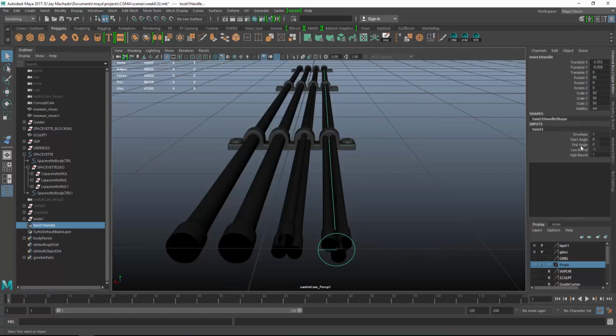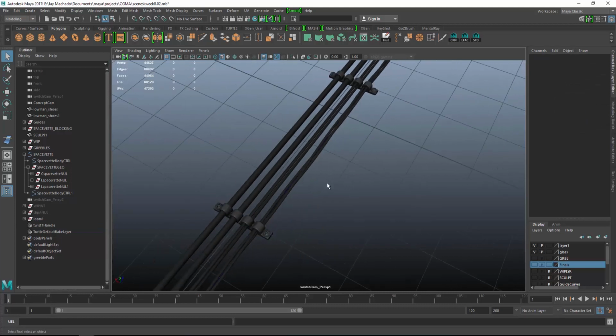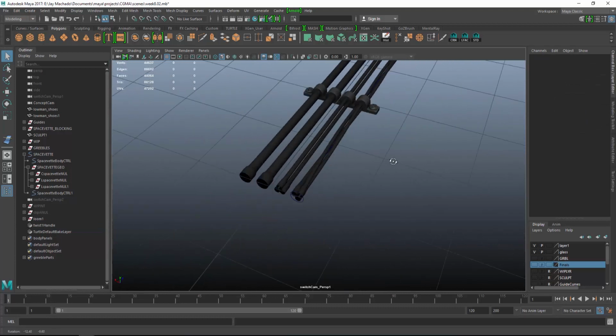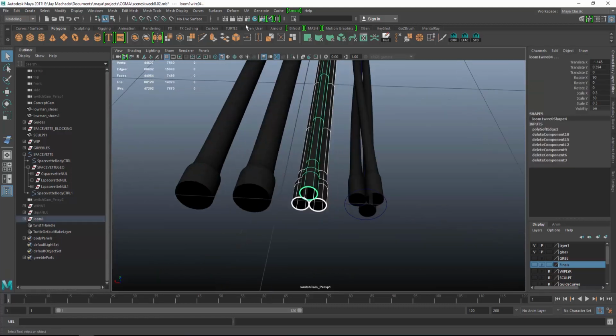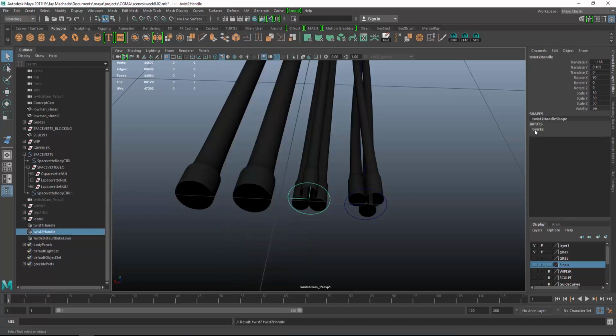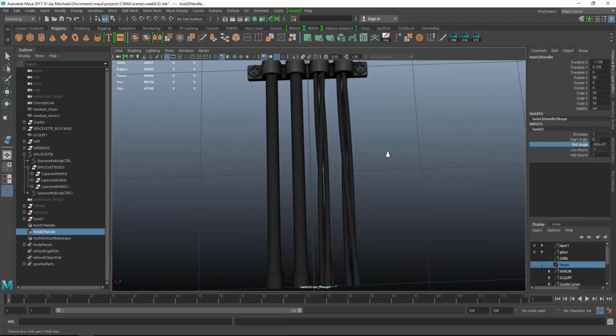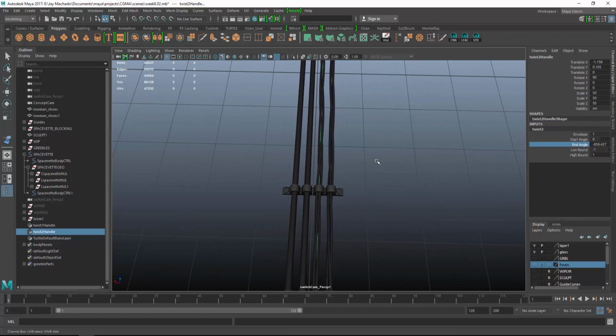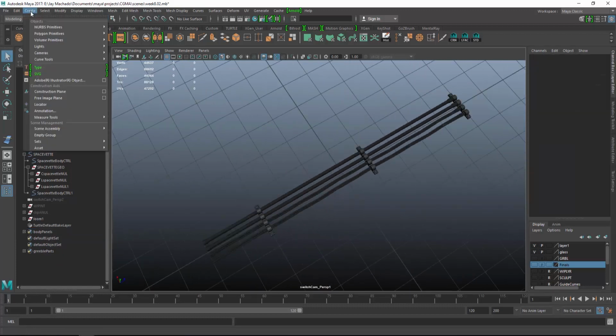And so now if I open this up and I just kind of drag the end angle, you can see that we're already getting a little more visual interest along this wire loom. So let me do the same with these three. Again, it's under the deform menu, nonlinear, twist. And now if I go over here and go to end angle and drag the opposite direction, we have some twisted wires for our wire loom. So let me delete history to get rid of our deformers.